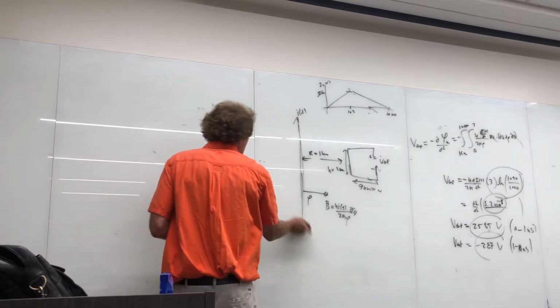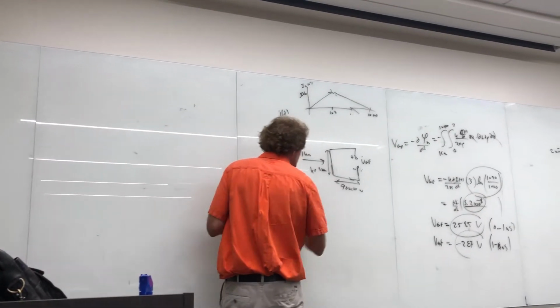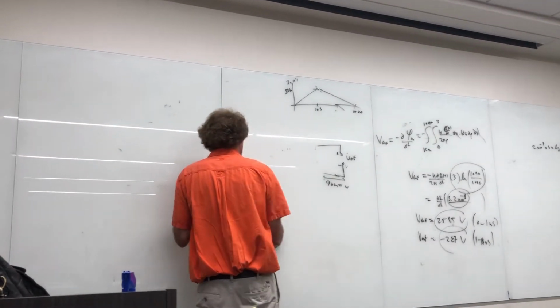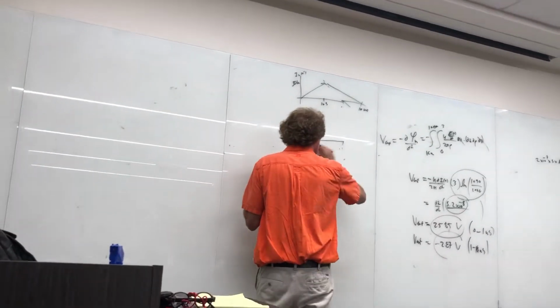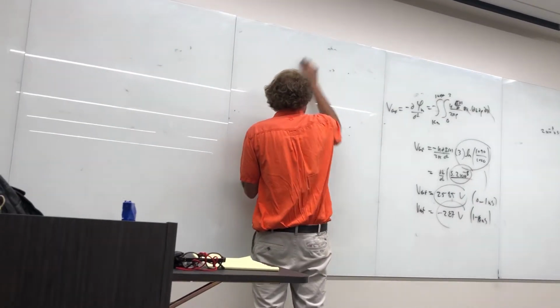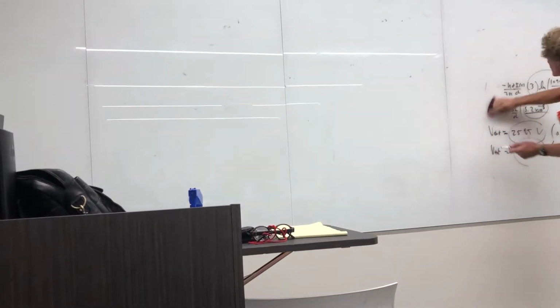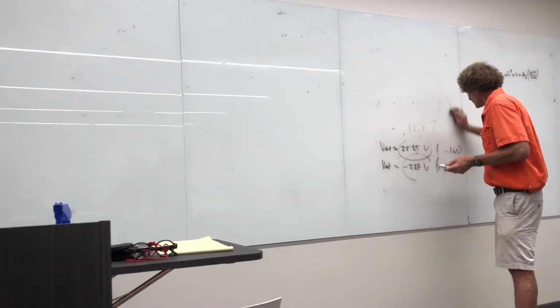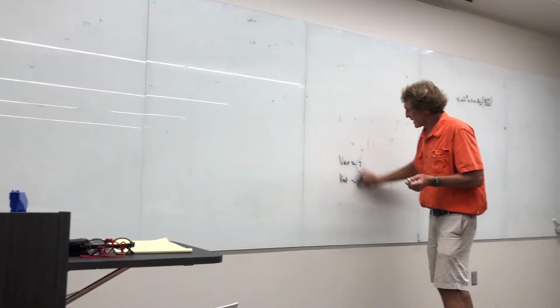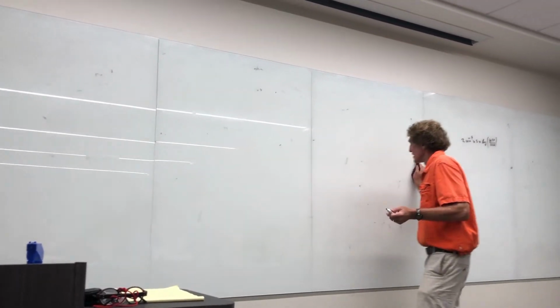Really, this type of problem, when lightning's distant like that and it's induced EMF, your house is set up for that. It's got all sorts of things that deal with that kind of problem, filters and stuff like that. But the real problem is if lightning hits a cable connected to your house.